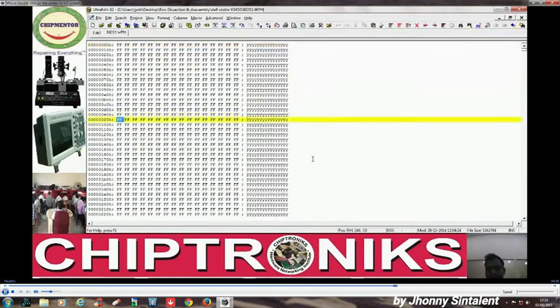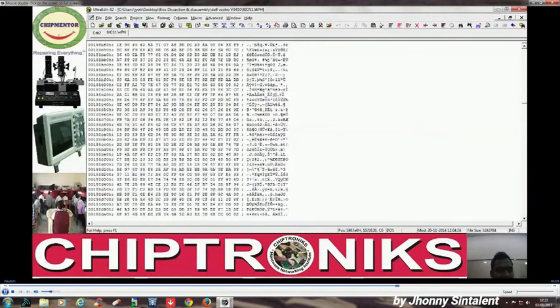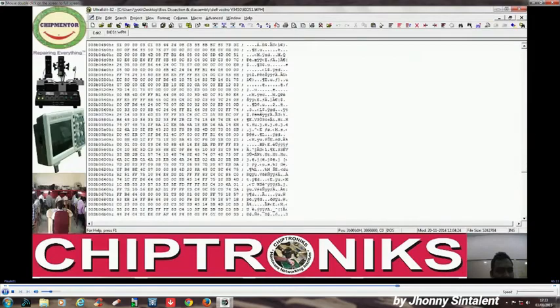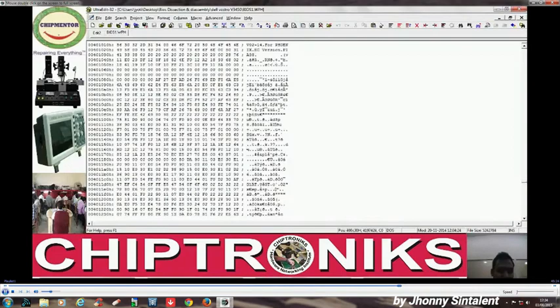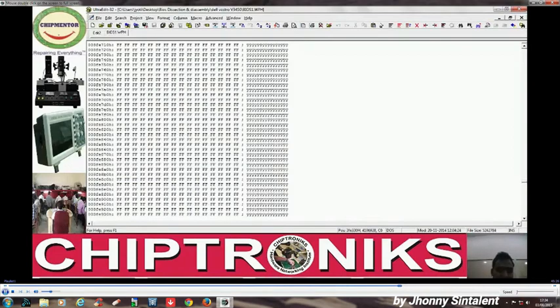All right. Now this is system BIOS plus EC BIOS. So what are the steps? We will have to move our cursor to 3FF over here. 3FF is 4 MB. The first 4 MB is system BIOS, the rest is EC BIOS. But then again there is a little twist. So let us first extract the EC BIOS, then we'll talk of the system BIOS, because this is EFI,